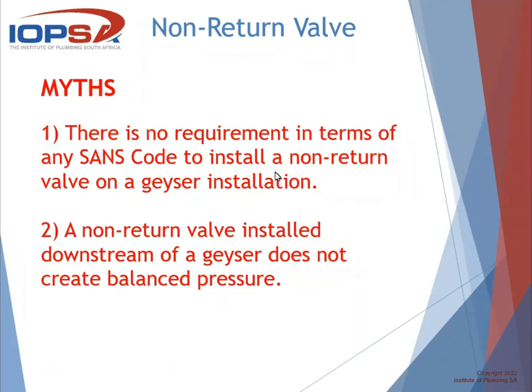So just always bear that in mind. And I know we're not talking about backflow prevention now, we're talking about check valves, but I just wanted to mention that a non-return valve is not a backflow prevention device. And a backflow prevention device is something that is deemed appropriate or suitable to perform a backflow prevention function.